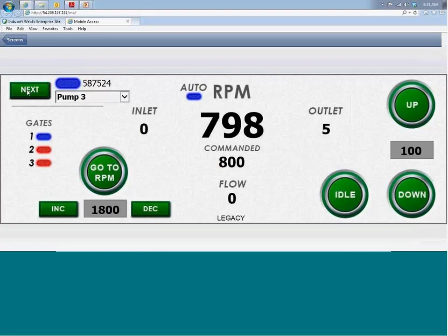Excellent. Thanks, Matt. Another question here: what type of hardware was used and how was the connectivity between all? Okay, so the hardware we used is basically Intercontrol, the line of hardware that we use. We use mobile rated components. These are all IP ratings of IP67 and greater. We used an HMI display that was programmed with CODESYS 3.5.